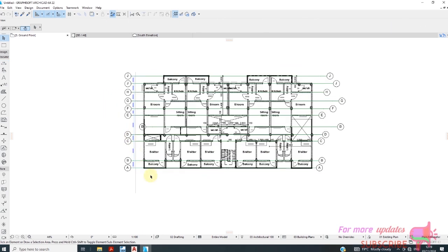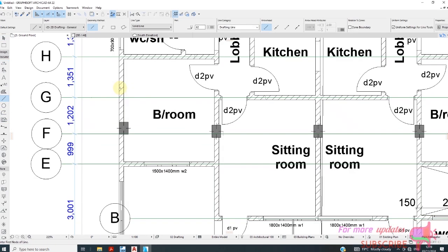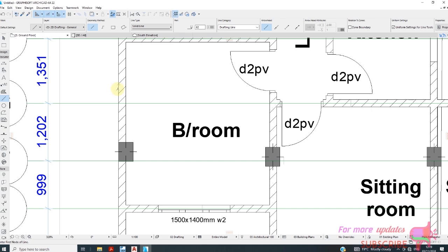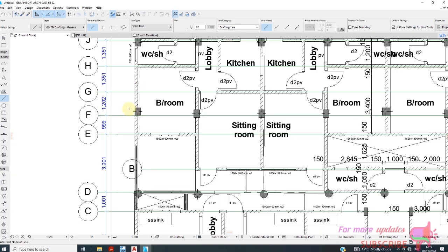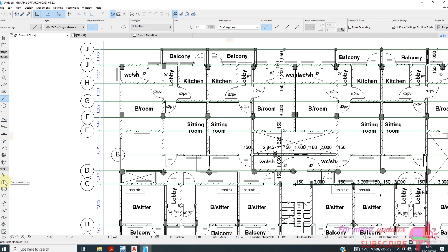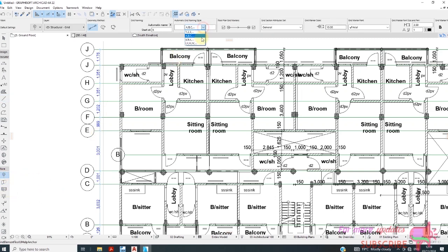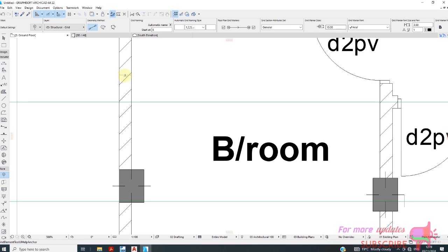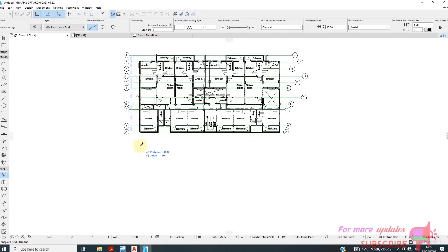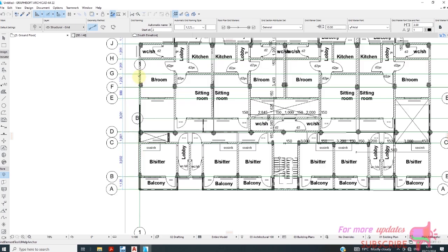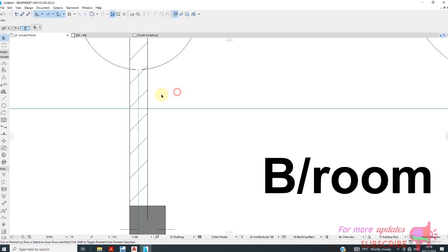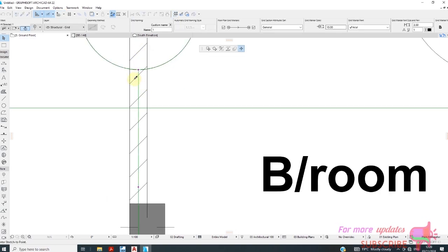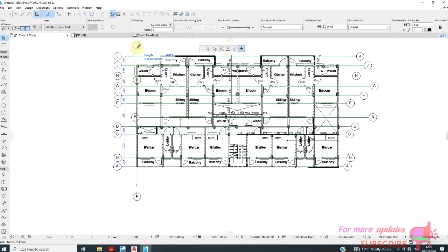Okay, now we can draw other grid lines in this direction, now in the y direction, in the x direction. So I will just activate the line tool, draw another line from that edge to that edge of that wall. Now activate my grid element tool, then this time 1, that point, holding shift, that point. Okay. Again, this one needs to be moved to that upside, holding shift.